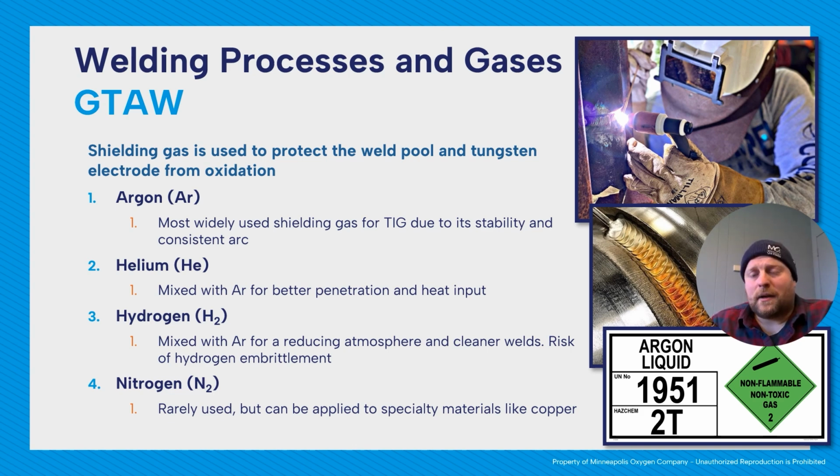When it comes to preventing gases from getting into our welds, people say water is an issue, moisture is an issue. It is, but more precisely, it's the hydrogen. Hydrogen is the issue. It's the smallest element, number 1 on the periodic table. So the smallest atom, it can really fit into anywhere.